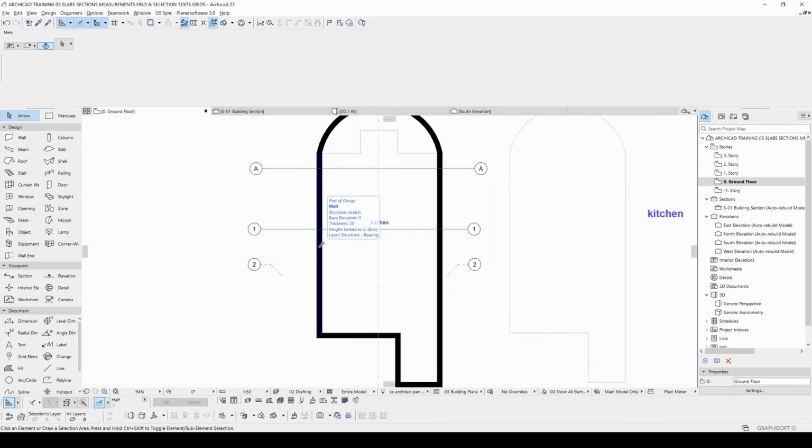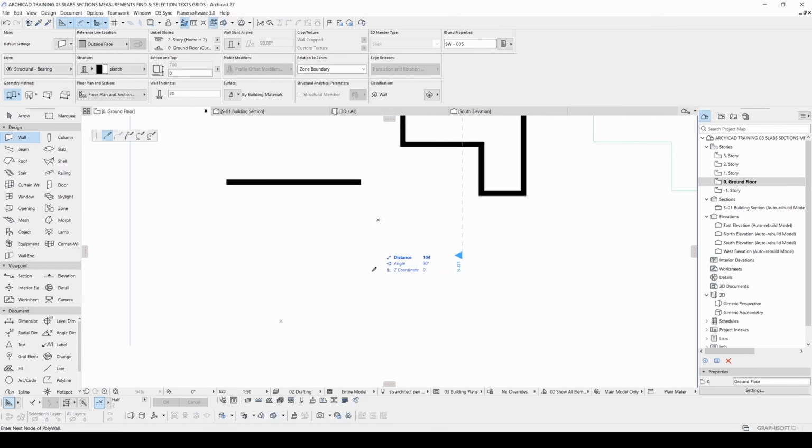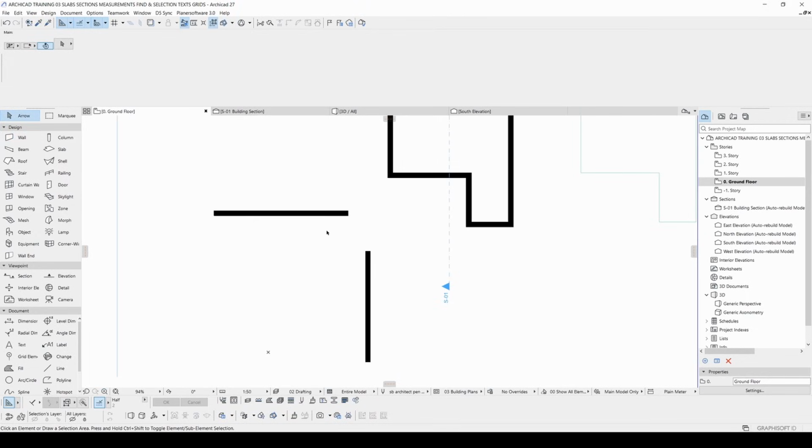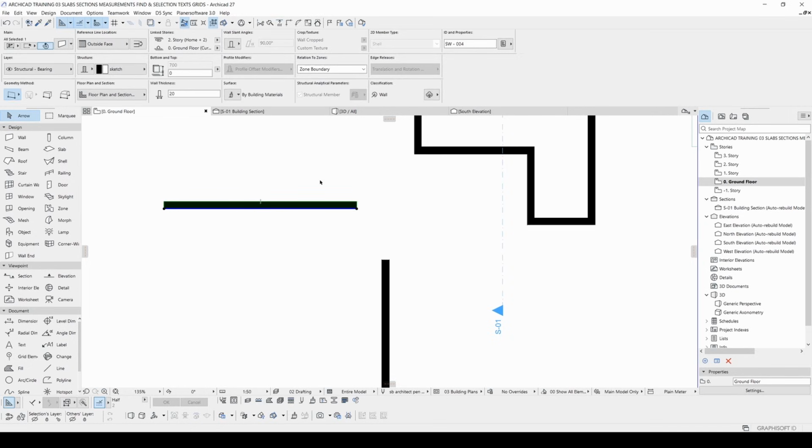For instance, I'm going to hit Alt and click this wall, and I'm going to copy that wall. And I'm going to create another. I will hit Escape, and you will see the arrow tool appeared, or you can click this arrow. I'm going to click this wall, and after that I'm going to hit Shift and click my second wall. After that, from this list, I'm going to click this Intersect. That's it. Of course, you can use shortcuts.